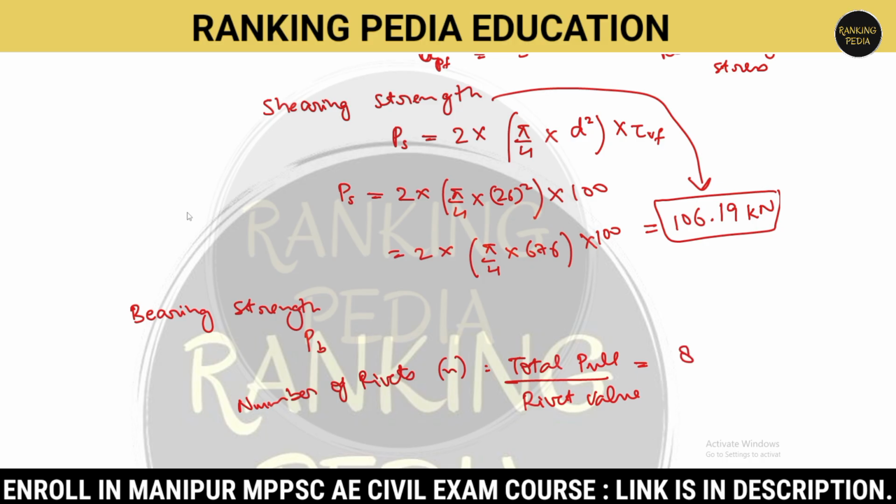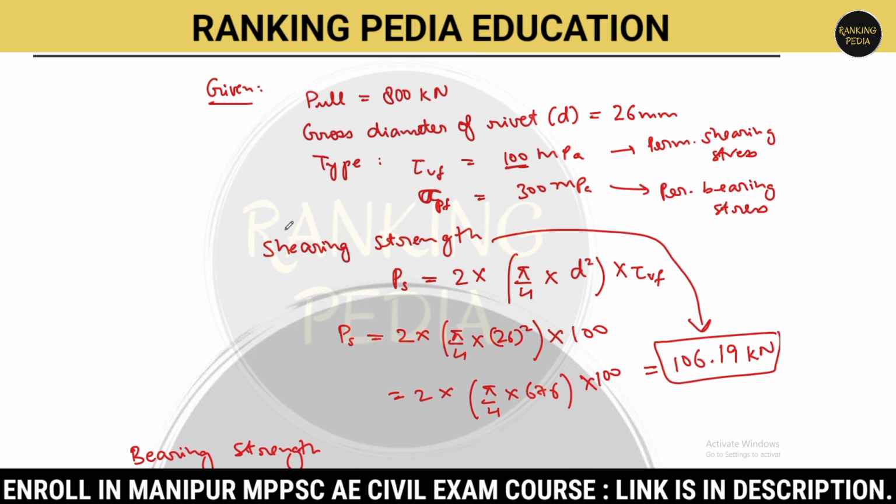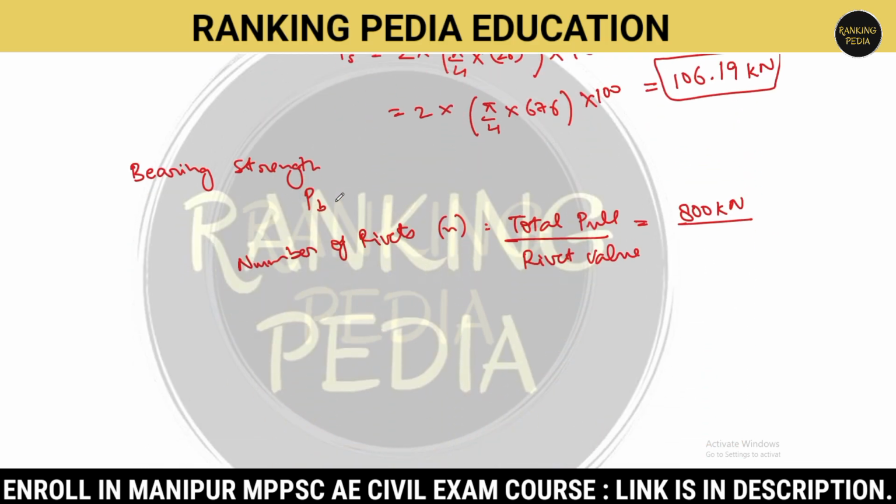Total pull is 800 kilonewton. Just mentioned over here, total pull, which we have denoted by P. You can denote it by P over here, or just write pull. Total pull is 800 kilonewton, and rivet value is over here, which is 106.19 kilonewton. When you divide 800 by 106.19, it will become approximately 7.53, or you can say approximately 8.